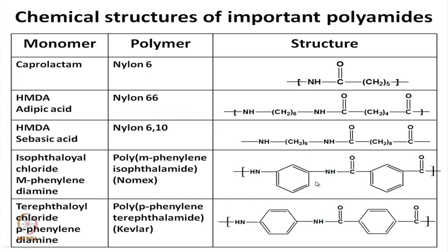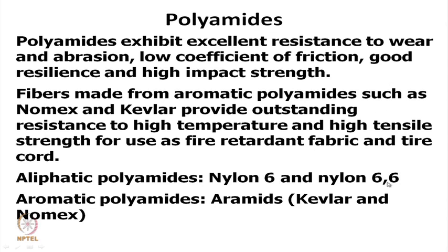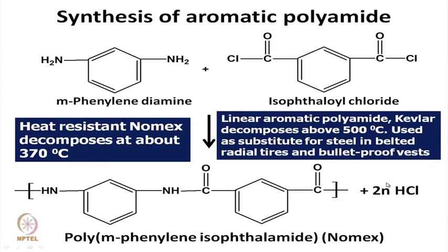If you go back to the previous slide, here you see the molecular symmetry is more than that found in Nomex due to the presence of the meta linkage. So, the thermal stability is obvious from the configuration of the polymer molecules, or the linkage of the amine and acid parts at the meta position for Nomex, at the para position for the Kevlar.